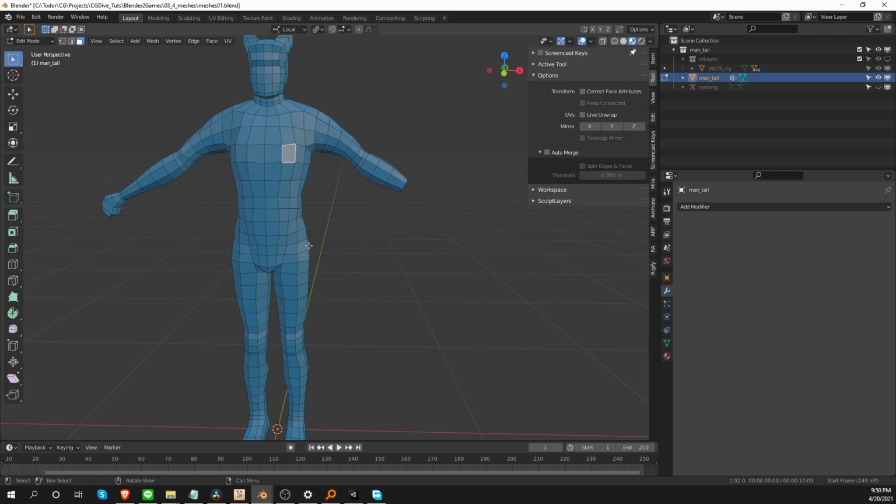And another area is when you try to export messy meshes to game engines. For one thing, the messy geometry, the overlapping vertices and polygons and so on, create needless data, and that will make your game assets heavier and less performant. But even worse than that, often the game engine may not even accept such meshes. It can give you some sort of error, and you may not be able to import the mesh. Now you should know some of the main ways and main tools to detect and fix bad geometry, and I hope this helps you create better quality meshes.